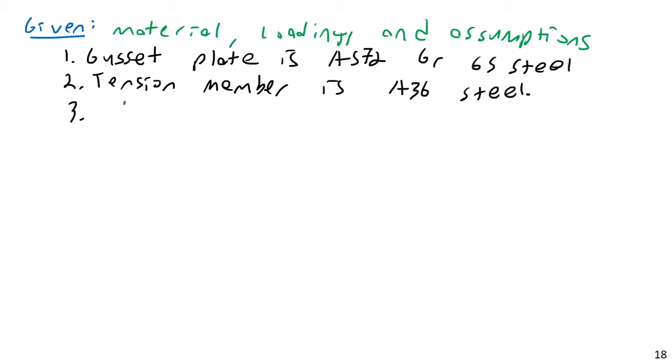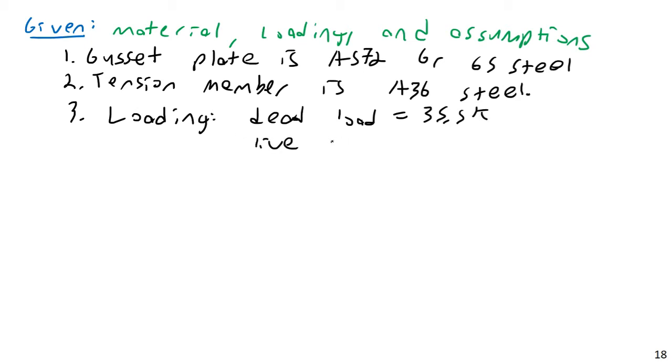3, the loading. Well, we have a dead load equal to 35.5 kips and a live load equal to 106 kips. And we are told the following do not apply. Well, I can actually just say the limit state of block shear rupture does not apply.